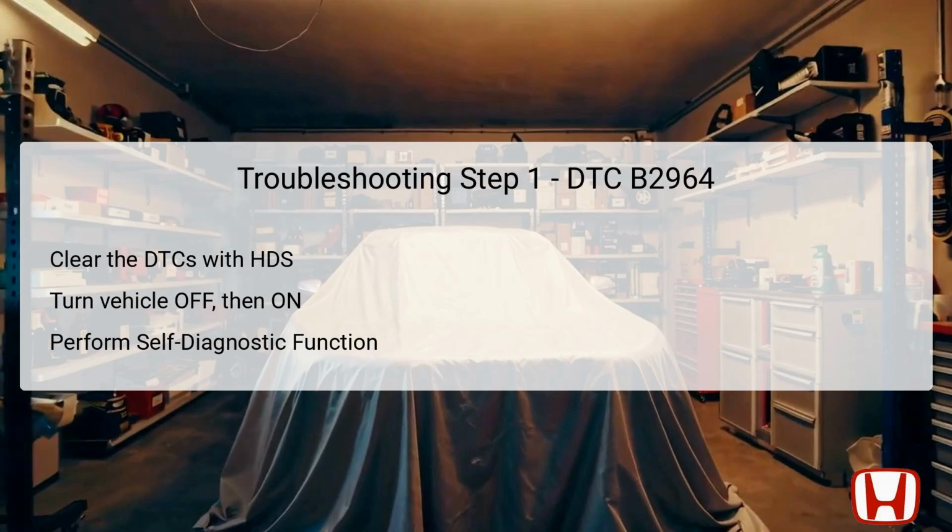The first step in troubleshooting DTC B2964 involves clearing the Diagnostic Trouble Codes, DTCs, using Honda's Diagnostic System, HDS. This tool is crucial because it resets the vehicle's computer and removes any existing error codes, providing a fresh start for diagnostics. After clearing the DTCs, turn the vehicle to the off or lock mode, and then switch it back to the on mode. This action helps reinitialize the climate control system.